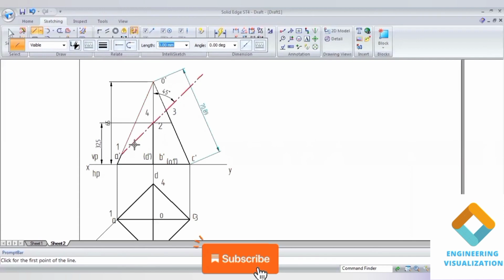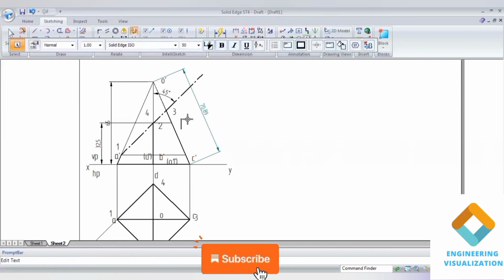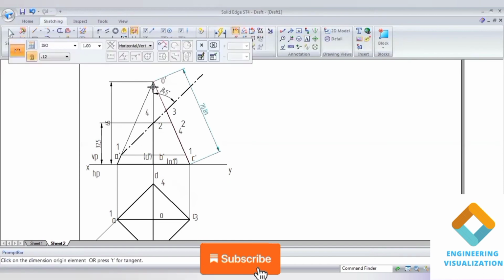Now we need to transfer all these cut points onto the slanted edge length. 1 and 3, this is an important step, guys. You should do it. 2 and 4, and 1, 3 are already there on the slanted edge. You need to measure these lengths because we need to cut the arc on the slant edge when we are drawing the development. We should know these dimensions. The slant edge lengths we need to find out.